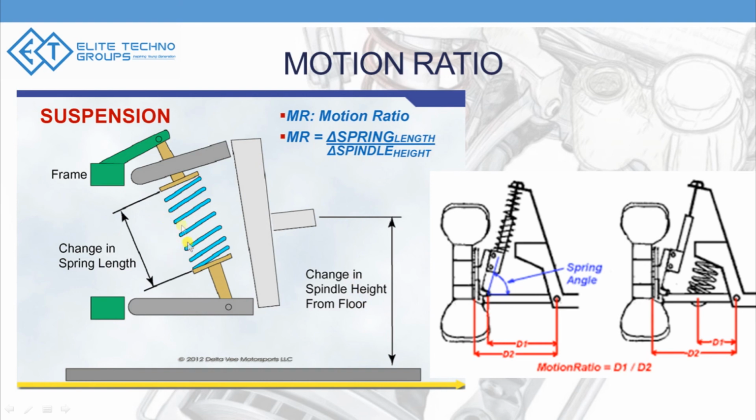So 2.5 inches is the maximum compression which I want the spring to overcome, and beyond that point, this compression is going to transmit the wheel going up back to the body, right? So for calculating the spring stiffness, you need to know what the motion ratio is.